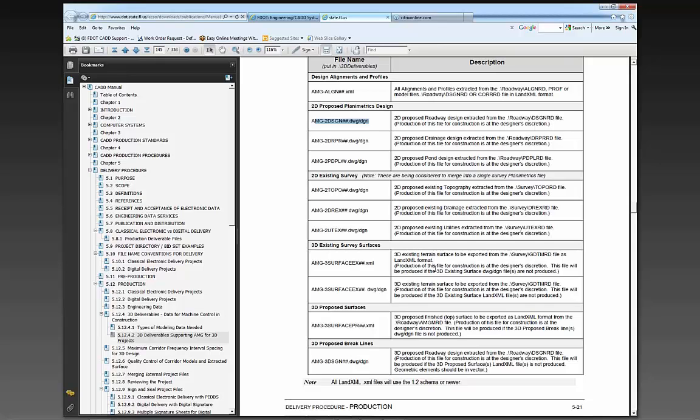The 3D existing surface was pretty straightforward. We just selected the terrain in that GDDTM file, did a save as, and got an XML file. I didn't do the whole save the DGN. You could just take that triangle file and place it over there. So the main point is you're trying to give them the dumb MicroStation lines that represent the triangles, so that if they had to, they could create it or import it and not create their own surfaces from the XMLs.